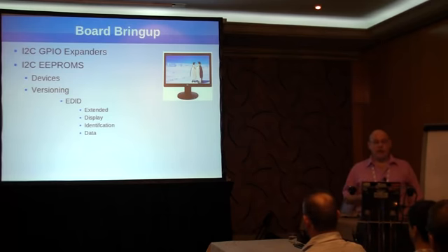So every HDMI that you work with, every DVI, and virtually every VGA that you work with actually has I2C on it that reads the timing information. So they actually have a complete standardized format that the information is stored in the EEPROM. Because every LCD panel has this, the prices on these and the standardization is out there. I mean, there's tons of them that are available.